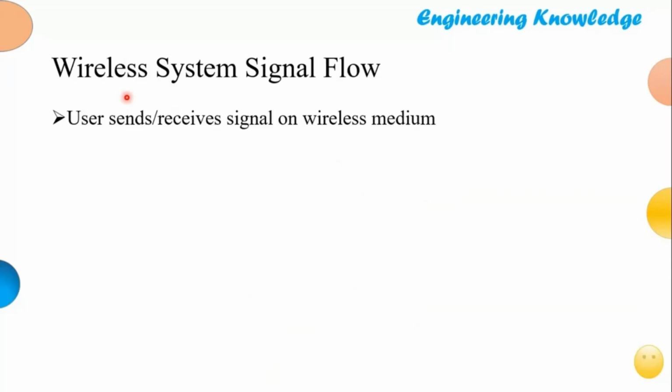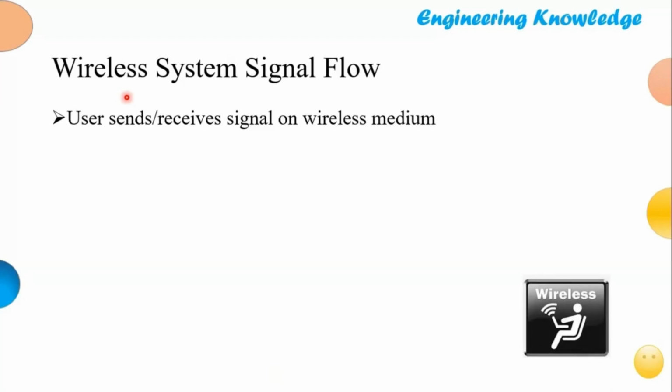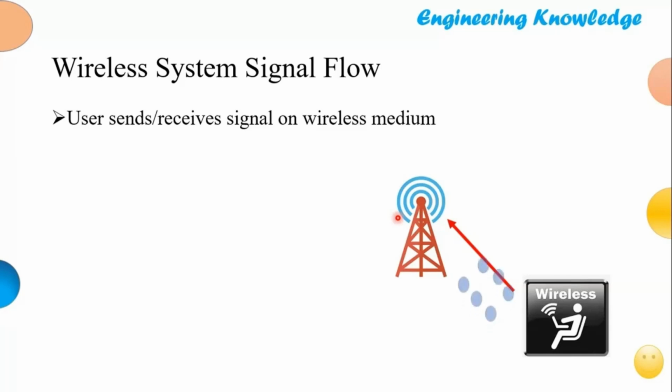Now, how do we represent this wireless system? There is a wireless user who wants to communicate, suppose, to the BTS. This is the uplink I am discussing here. This transmission takes place in the presence of h, which is the fading. The signal is attenuated and delayed due to multipath propagation, and apart from that, there is also omnipresent additive white Gaussian noise.